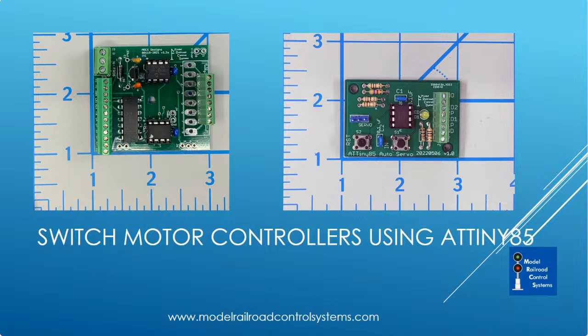Here's a switch motor controller my late business partner, Chuck Catania, developed, and it's a locking controller. So what happens is, if you've got a CTC system, there are cases in which the dispatcher would like to release a switch at, say, one end of a siding, so that a local can work that without having to constantly call every time they need the switch moved.